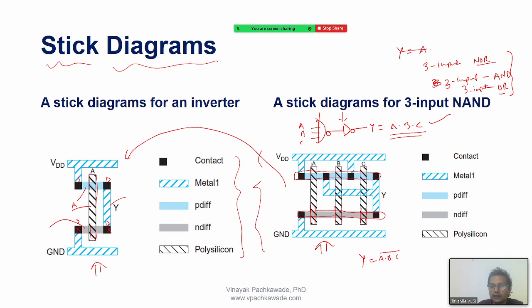Why can't we, there was our discussion about why can't we just use it without an inverter, right? Yes, sir. And what was that discussion? So again, I went through some of the information. There, I didn't find anywhere that without an inverter they are constructing a NAND gate. But as per earlier discussion, if you do that, that is acting as a buffer. And you said that that buffer you cannot use, because it will not provide a strong zero and strong one. Maybe by using that method, we may construct an AND gate without inverter.